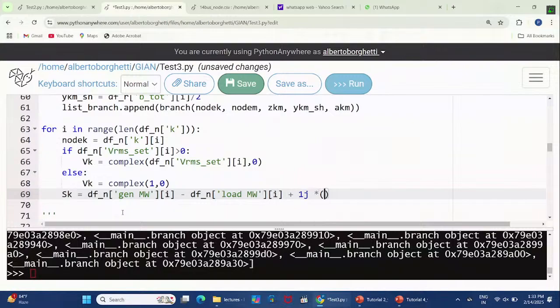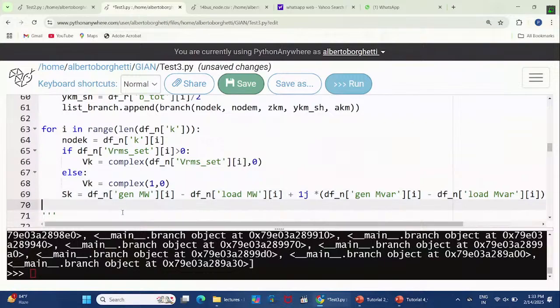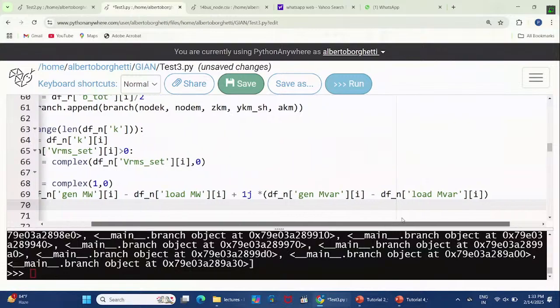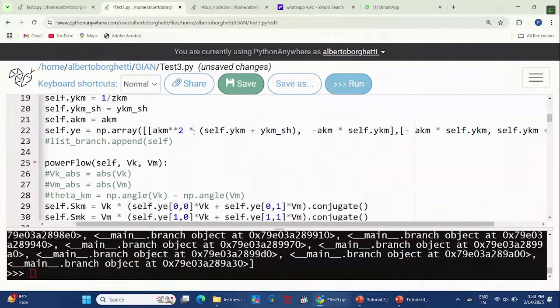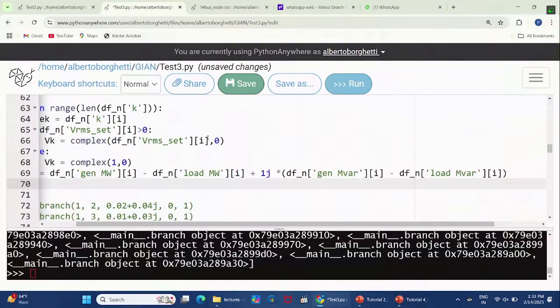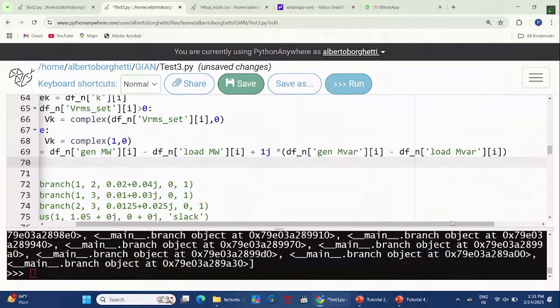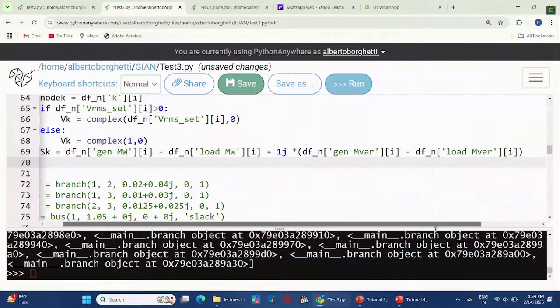And then here in parentheses there is no megawatt but mvar, and this here is in var. We have seen that we divided the power from P base in the object, so we don't need to divide here because our object takes already the megawatt.